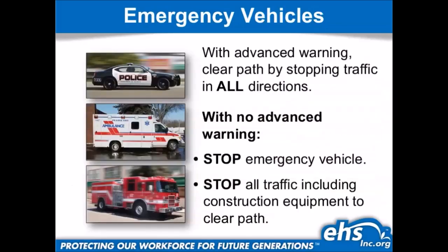Now, I mentioned emergency vehicles. With advance warning, that means you hear the sirens at a distance. You have to treat it as if that emergency vehicle has to travel through your work site. So when you hear the sirens, you're supposed to stop traffic in all directions until you no longer hear the siren, so either they've gone through your site or they've taken a different route. Once the emergency vehicle has passed, you can allow traffic to flow again. Whoever last moved, the opposite end goes through.